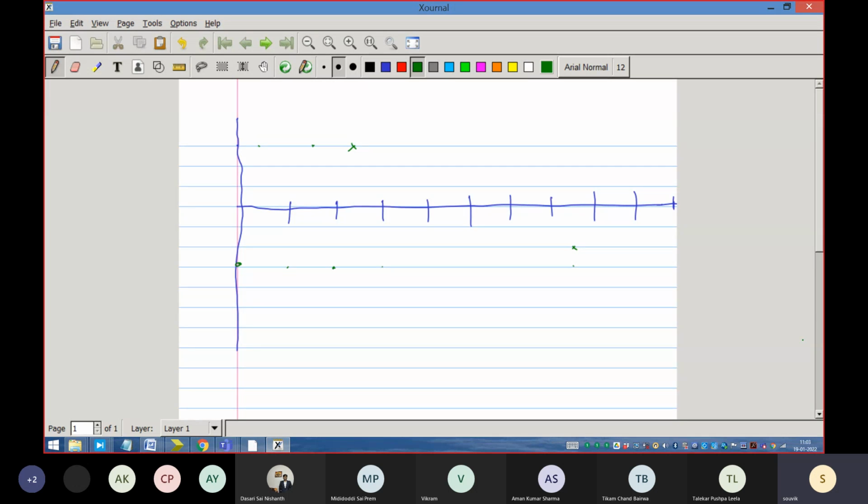Therefore, in that small time period, the sine wave magnitude can be conceptually thought to be constant. So this is the basic idea: we think that it is constant, so it's a constant voltage. We forget about how the sine wave is varying subsequently. We just look at that particular switching period. We only acknowledge that it can be positive voltage or negative voltage, and the switching should be such that it is able to produce positive or negative voltage, as the case may be, as the instantaneous value of that sine wave is over that switching period.